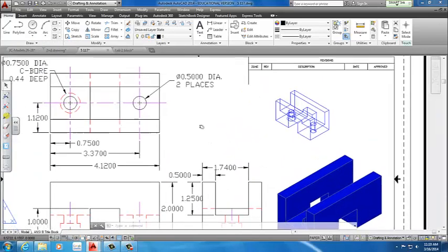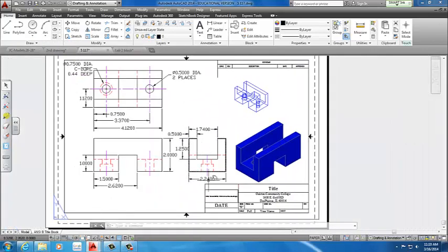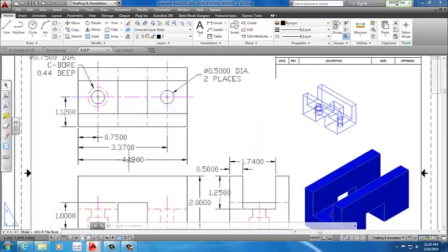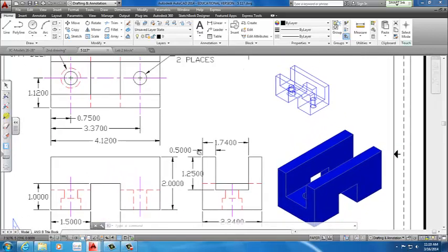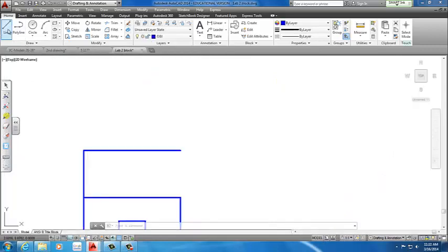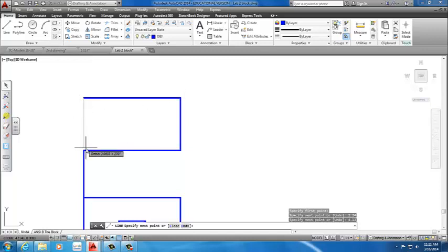We select the center of the circle. We make a vertical line, but right now it does not show it can see that my line is on the right side here, which is vertical, 90 degrees. Total depth is 2.24. So I have to make sure we have the ortho on, allowing me to make this line right here 90 degrees, 2.24. So I create the line 2.24, and again, I'm going to go across 4.12. That should allow me to close my box.